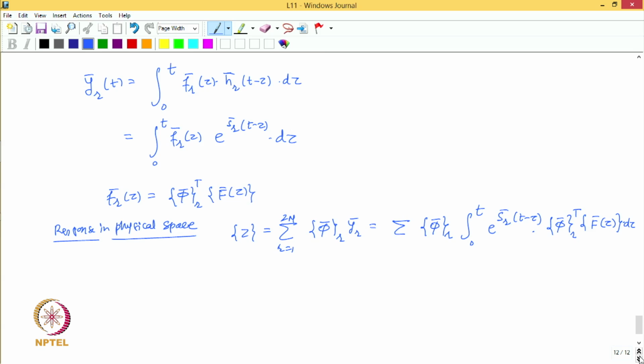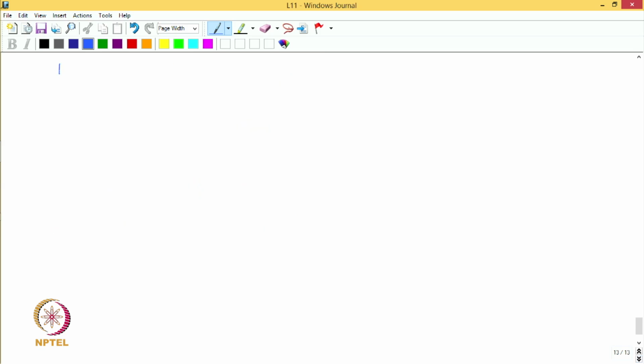Let us define now the impulse response function for this system, and we would like to find out what is h j k. This we would like to find out the response at j degree of freedom if the force is acting at the k degree of freedom. So, we again use the expression we got previously, and we basically define the force vector now.